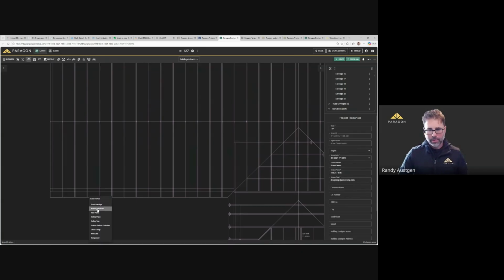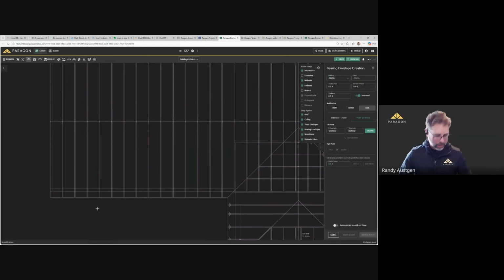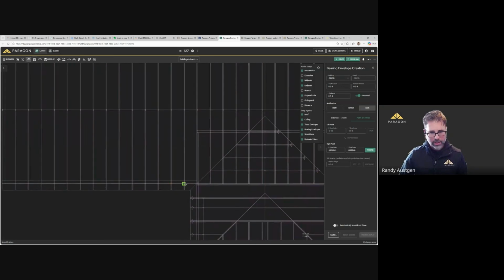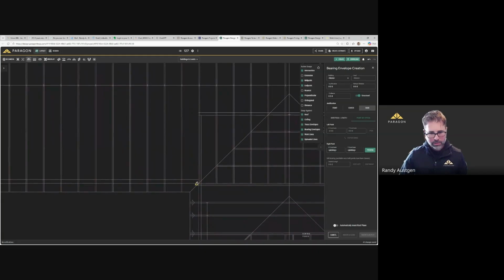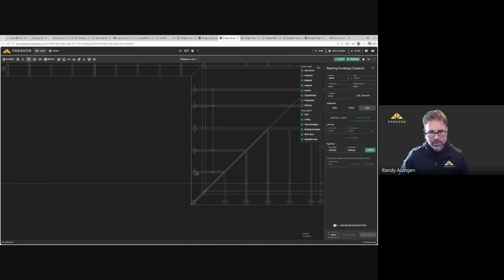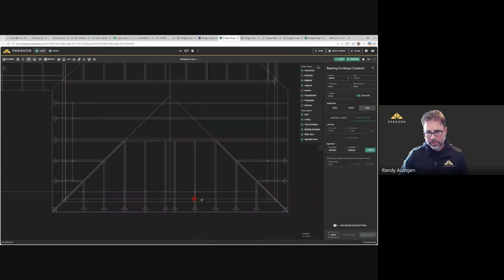And then just to tag onto that, I'm going to tie a few things together. So we imported lines. You could just as well import an underlay. I got distracted, my bad. And what I'm going to do here is I'm going to go into bearings. We'll go to point, and I'm going to use that trick or tip to hold down Alt. You got to be careful here to make sure you're snapping to the right things. Hold down Alt, and so on. It's tracing over those lines.